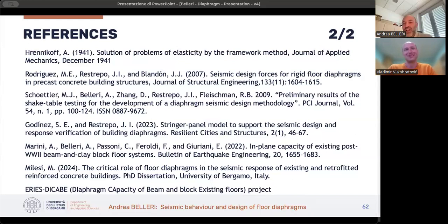At the beginning, we were thinking about using, because this project involved different testing facilities, some of those had also shake tables. Also in New Center in Pavia, we have one, and a big one in Bergamo in Ismes. But the point is that to do a small scale we need to place, for a similitude law, additional masses.